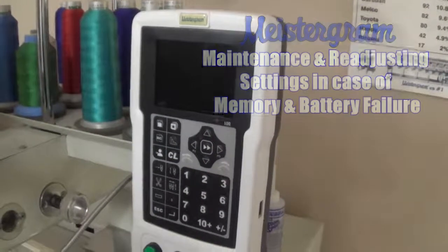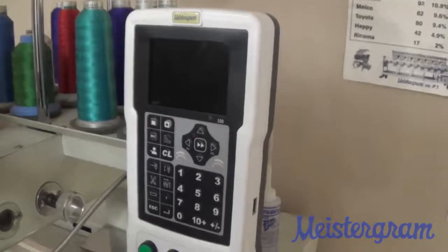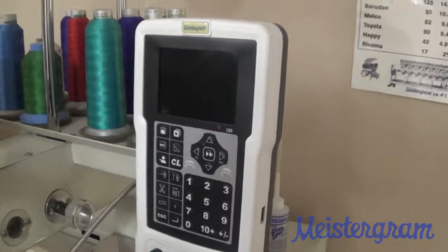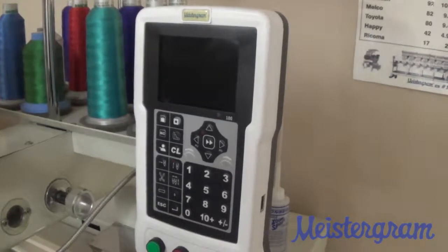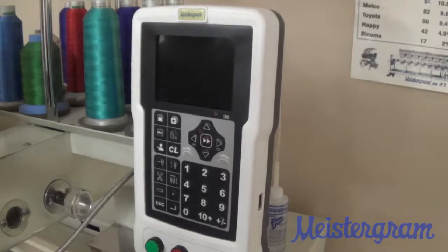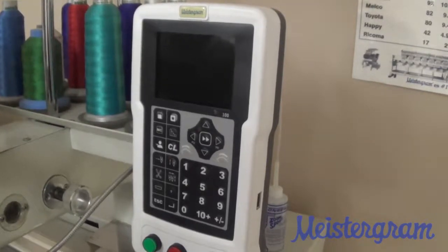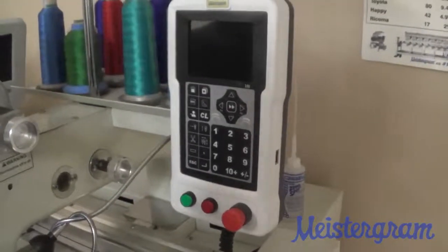So this is for the people having issues with the change of language on their screen. You don't understand what it reads when you power on the machine, and a few other problems that arise from this. This is due to the machine losing its preset memory. This is caused by the battery on the main board having a low power or having no power whatsoever. So if you do have these issues, go ahead and replace that battery.